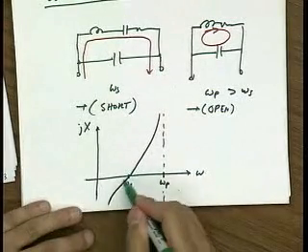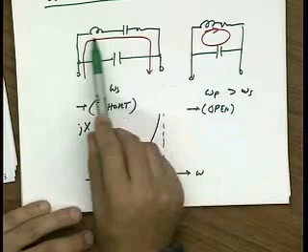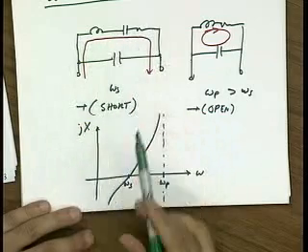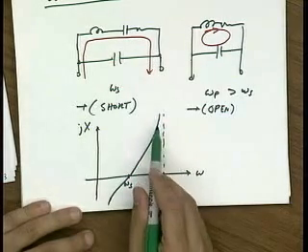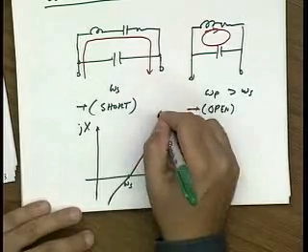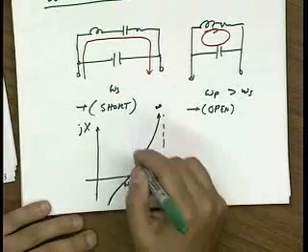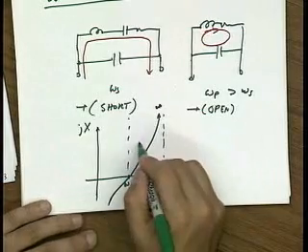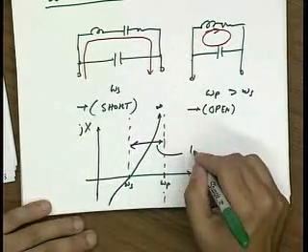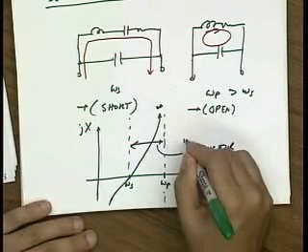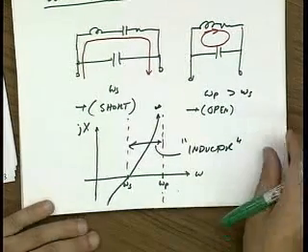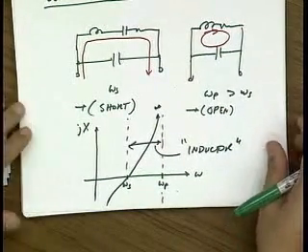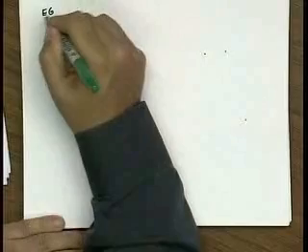So I go from a capacitive circuit at low frequency, right? At low frequency, this branch looks like a capacitor. This is a capacitor. They're in parallel. I hit series resonance. The reactance goes to 0. And then I go to parallel resonance, where this basically just shoots up to infinity. So the key point is that in this region, the crystal looks like an inductor. Okay? That means that to build an oscillator, all I have to do is replace my inductor with a crystal.